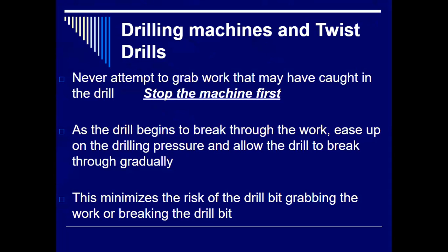As the drill begins to break through the work though, if you are drilling and you feel it start to come out the bottom, and with metal drills, you can hear a couple little cracks. It'll lighten up a little bit. That's you popping through the bottom of that plate. Ease up a little bit on the pressure and just allow the drill to come through gradually. Don't force it through. It's not going to work out well.